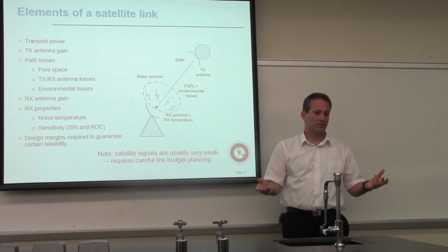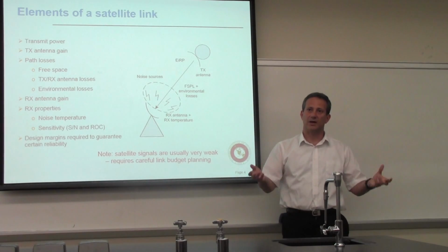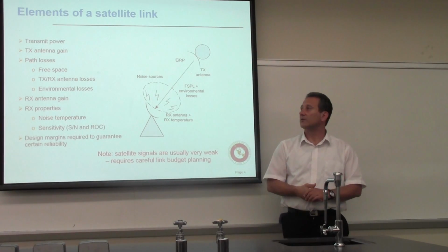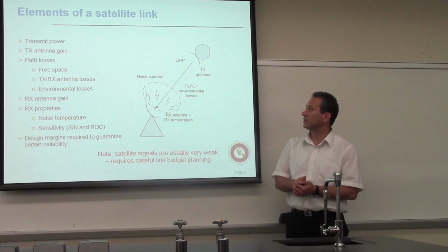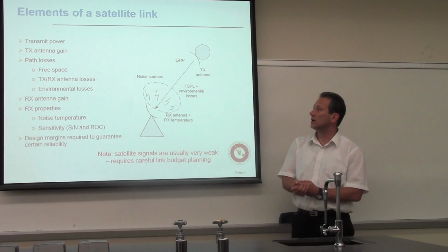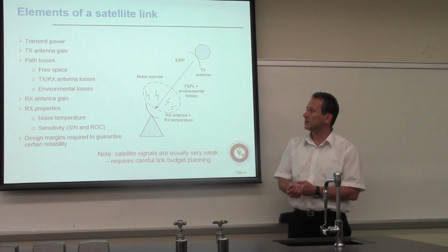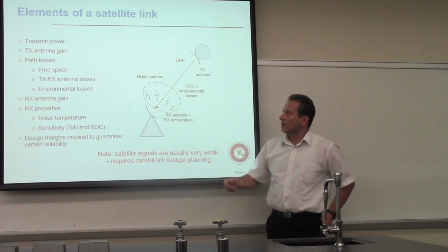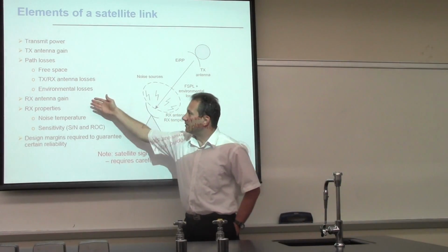Then the second thing that needs to be dimensioned and selected properly is your antennas. And we saw that this is a balancing act between the gain, size, and the pattern of these antennas, and what it is that they need to cover. So you take all of these into account during the link budget analysis. Now, I guess transmit and receive antenna.